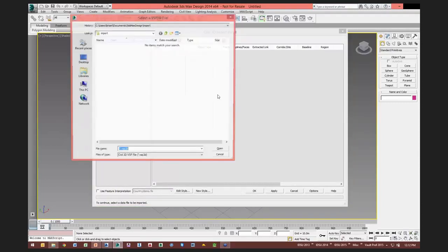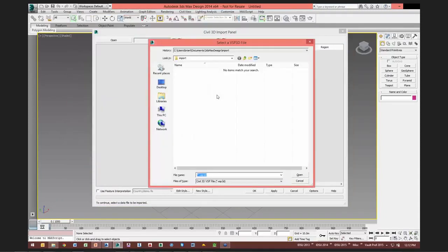While I'm browsing here, one question came in. Can you enter multiple link codes to the filter? Absolutely, you can. And you would separate them with commas in the same way you would put multiple link codes in a subassembly's properties.